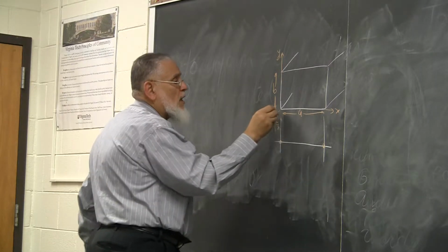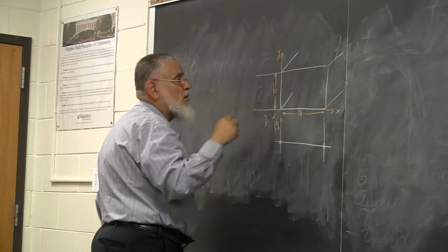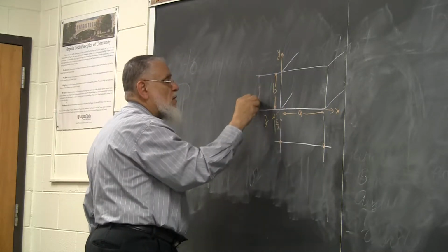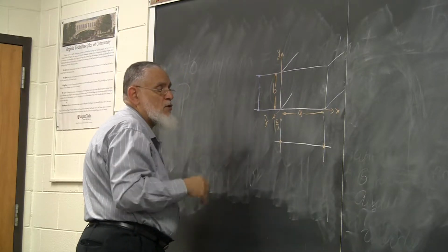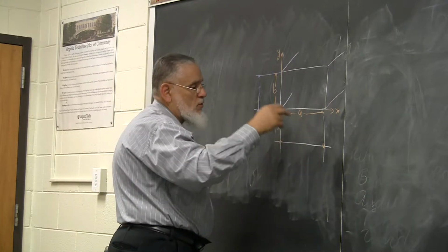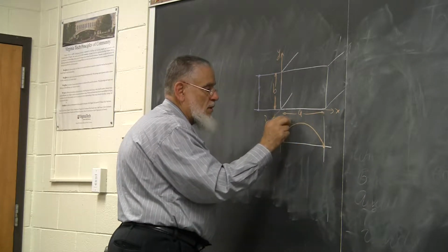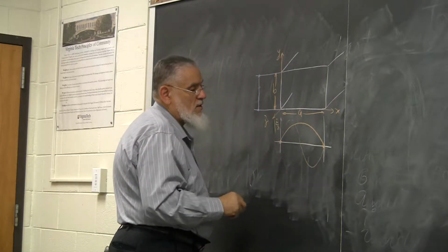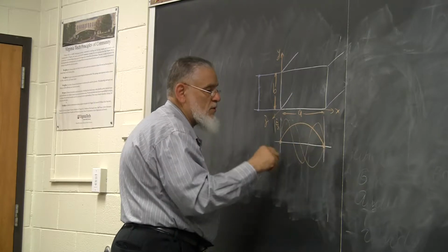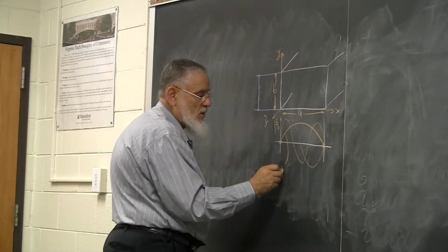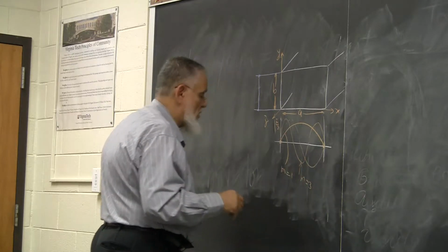And along the y-axis, we had a similar situation. Again, the E sub z is tangential along all these points, so it has to be 0 here, and 0 there. And the equation showed that we end up with sinusoids, because of the zeros, obviously. So we can have this distribution for the E sub z, or possibly a second order of it, or a third order. All these are possible solutions. So we said m is equal to 1. This one here is m is equal to 3, and so on and so forth.